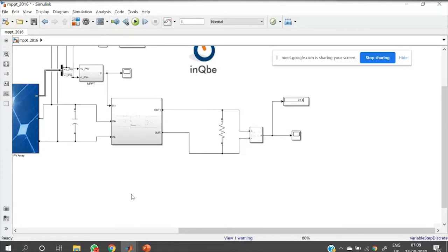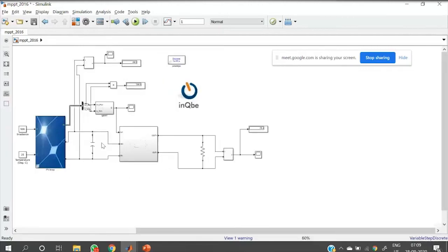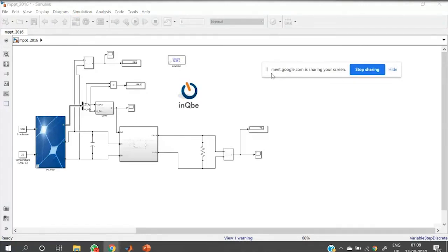Good evening, sir. In partial shading conditions, we have experienced multiple power points and tracking of multiple power points. Suppose constant irradiation changes are coming, then the DC voltage will not be constant. And if you are connecting a water pump or a motor at the output of the DC to DC converter, there will be disturbances in that motor or that converter. In that case, what do we have to control, the BLDC motor, or that output DC to DC converter, for getting a certain range of output voltage in case of partial shading?